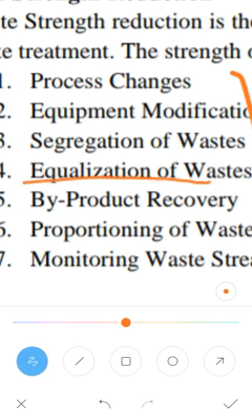If you take an example, manufacturing requires a series of operations that take 8 hours. The plant needs an equalization basin designed to hold the wastewater for an 8-hour period. Effluent from the equalization basin is much more consistent in its characteristics. This stabilizes the pH and biological oxygen demand and settles the solids and heavy metals, which are among the objectives of equalization.